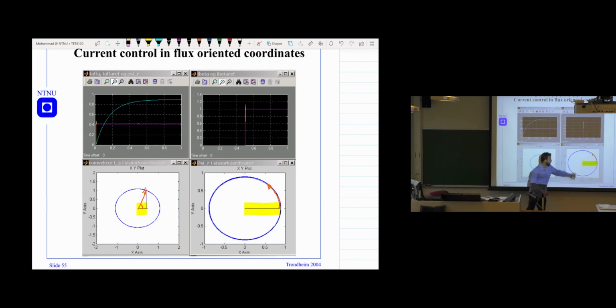This angle is always forward. So when this CR comes to this position, like for example here, this means the rotor current vector comes to this position, because it always maintains the phase difference, the angle that it initially has. Initially when it was 0, and then you see that it has this angle, something like this angle delta. So when CR comes to this position, then the current vector is here. So this is now rotating. Any question here?